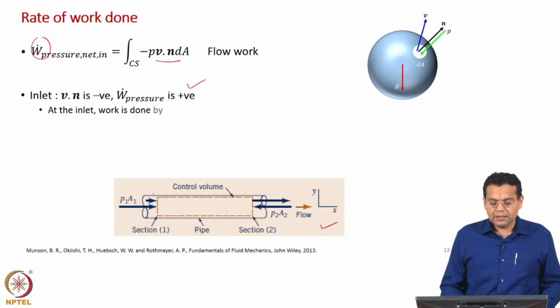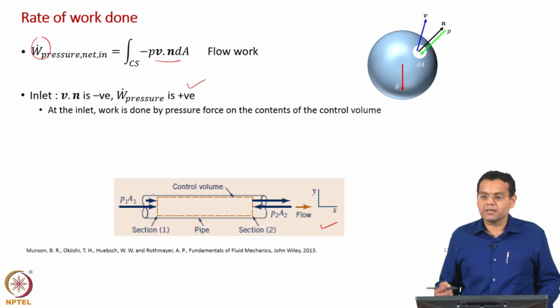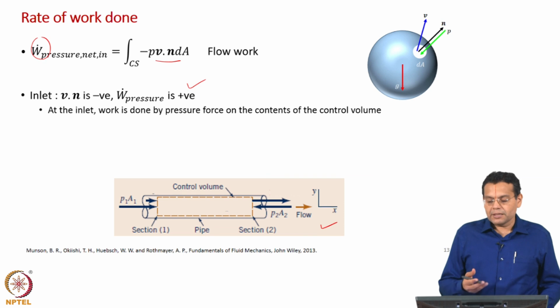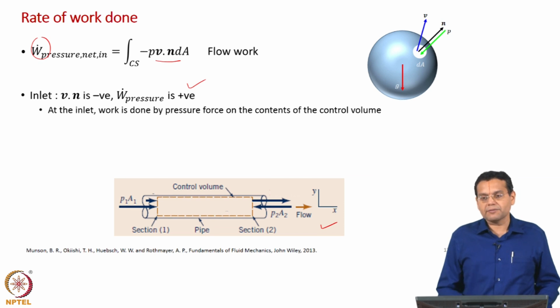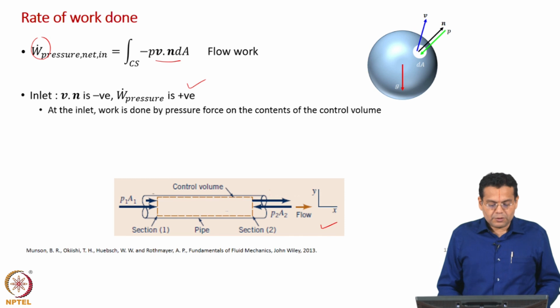At the inlet, work is done by pressure force on the contents of the control volume. Because it is positive, work is done on the contents of the control volume. As I have told earlier also, more precisely we should say contents of the control volume. Now, which means that the pressure does some work in pushing the fluid into the control volume.